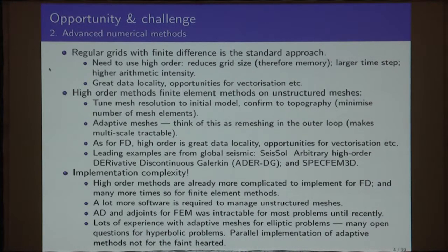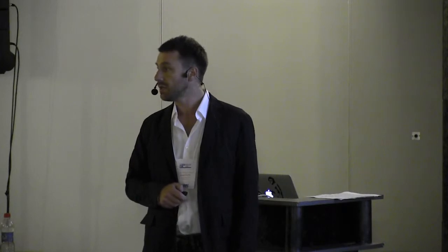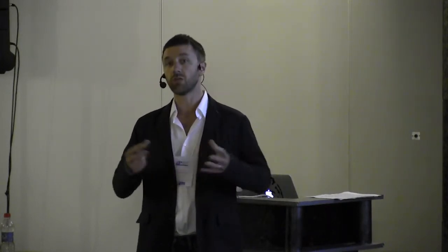And then, of course, if you take that step, it's only another small step to start using some type of error measure, like a residual or some measure of the error in your solution, whether that be your model or whatever else. You can define how that best should look, and then use that as a guide to decide, well, what is an ideal mesh for this particular problem?